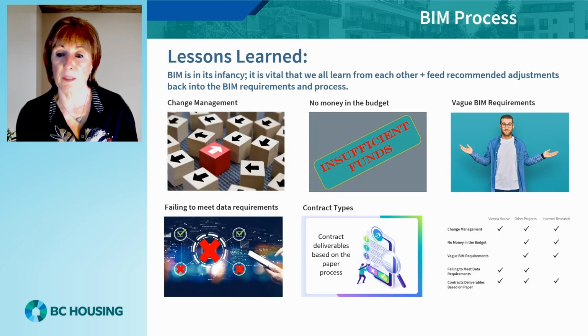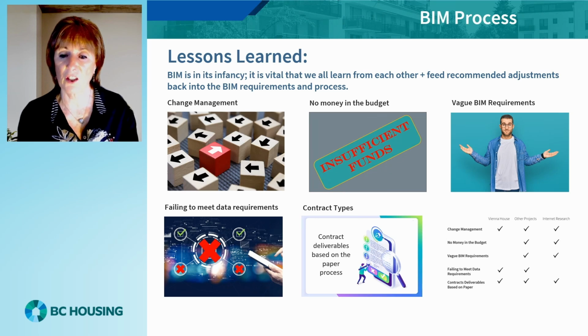From a lessons learned perspective, there are 5 key aspects that need to be considered. Change management of the people and the process, ensuring that funding has been made available to support this new digital process, ensuring that BIM requirements are precise and clear and that issues flagged during compliance audits are resolved. Finally, consider the contract type when asking for a BIM process. BIM is collaborative and requires sharing of models, datasets, and information.